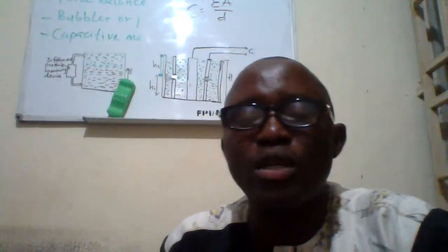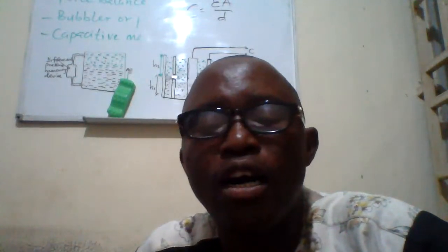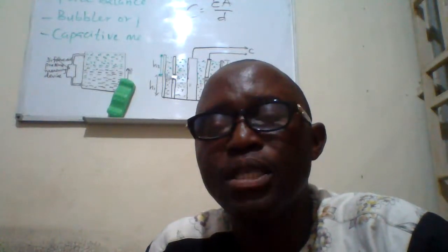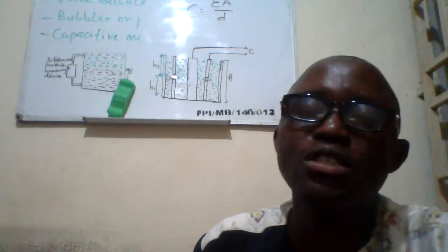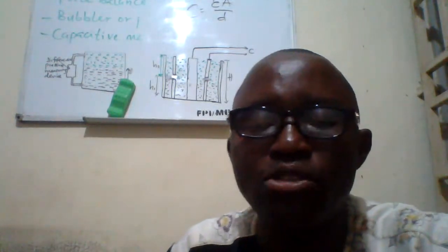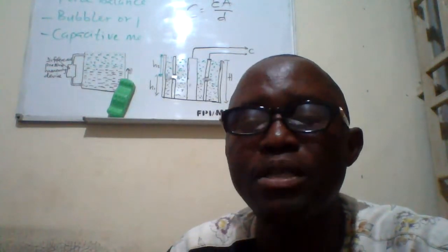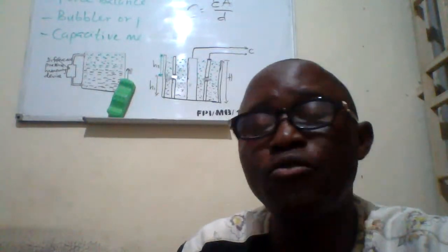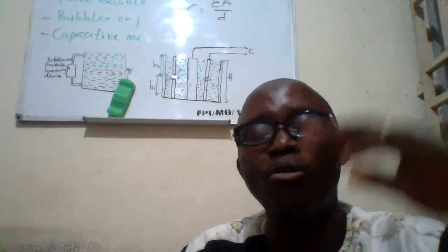Now we can have that system in that manner, so that we can have H of liquid, H of gas or air. Then we also know that because there are two different dielectrics, we have two different permittivities. Permittivity of the fluid, which is dependent on the type of fluid that we have in the tank, and the permittivity of air that is above the liquid.